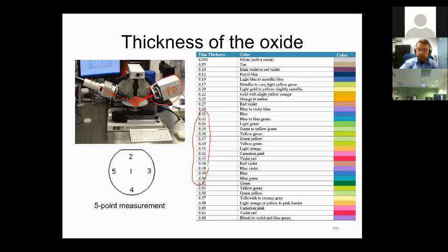So you put your wafer next to charts like this, and then you try to associate the color that you see coming from the wafer with these color charts, and then you say, okay, so it might be 0.34 micrometers. So I'm just going to enter that guess and then let the ellipsometer take care. If it is in this vicinity, it will give you the result in angstrom level. So that's as powerful as it